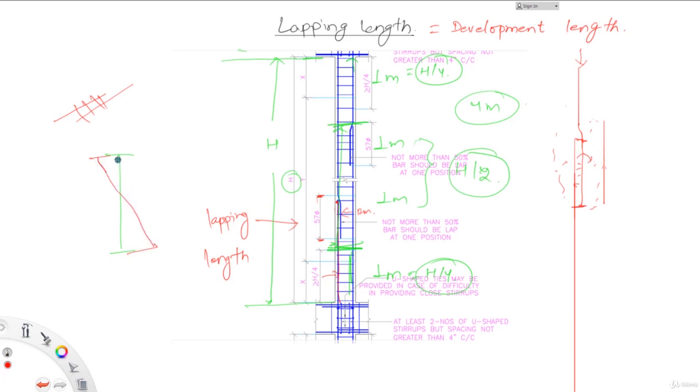You can see that the bending moment is high in the upper region, high in the lower region, and comparatively less, even zero, in the middle region. So the bending moment is lower in the middle region. Due to this reason, we provide the lap only in the middle portion of this column. In the column, we provide the lap in the middle H by 2.